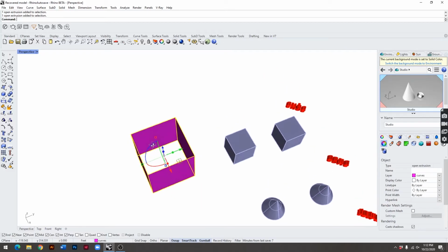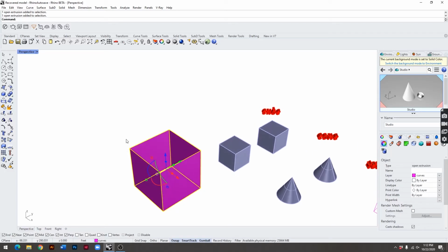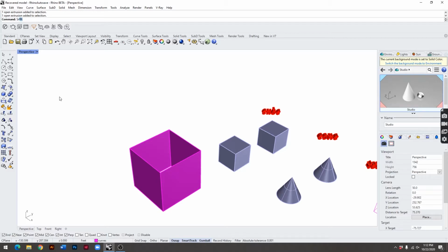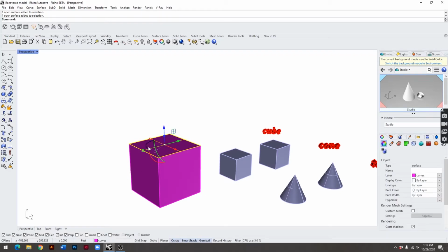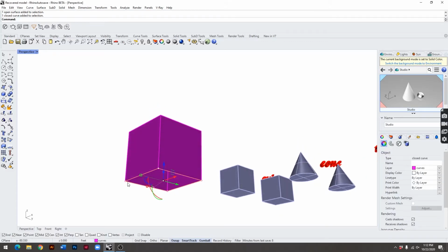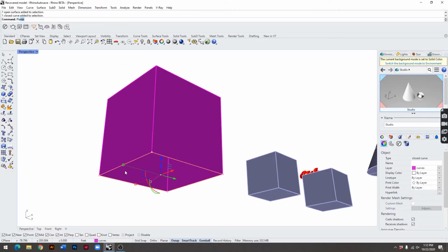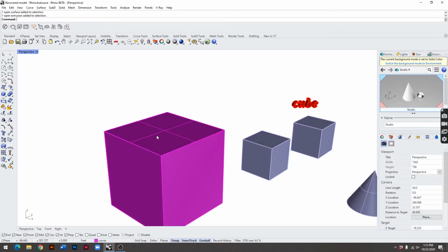And in order to get this open extrusion to a closed solid polysurface, we will either type in the command SrfPt, and that will ask us to specify a surface using 4 separate points, snapping to each corner, and that gives us our cap. We can copy that to the bottom, or just to try another route, we can click on that base curve that we specified and type in planar surface, press enter, and now we have both a bottom and a top cap.